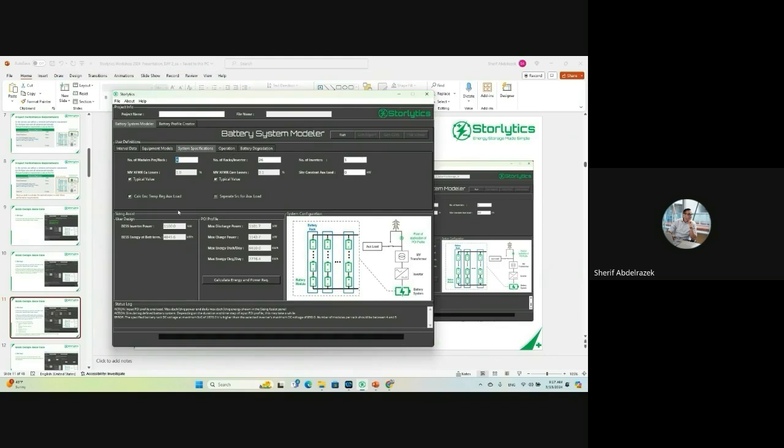All right, so we put in the medium voltage transformer loss values and the site constant aux load. For simplicity, we'll just assume that's 0 for now. And here, as mentioned, we'll allow the software to calculate the enclosure temperature regulation load, which is, let's say, more than 95% of auxiliary load on site.